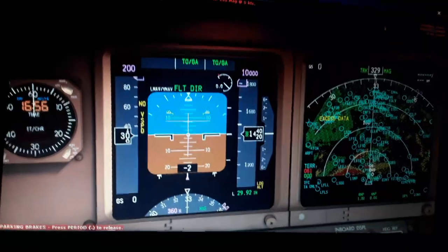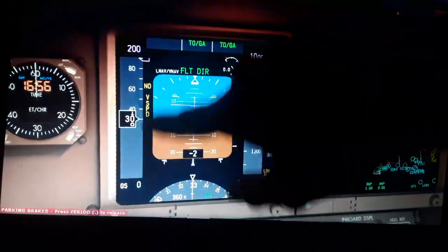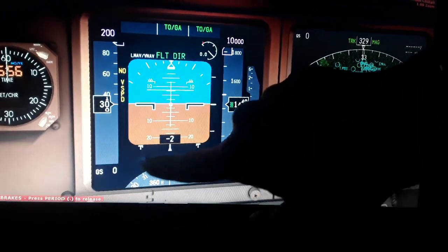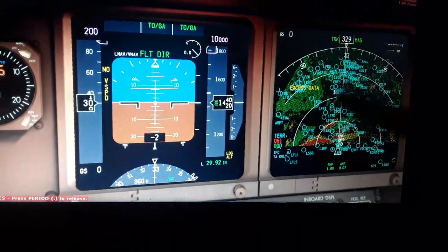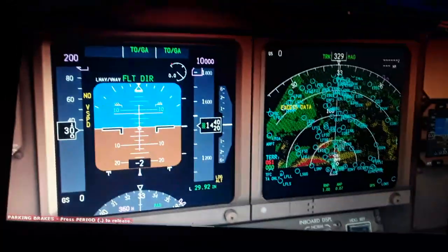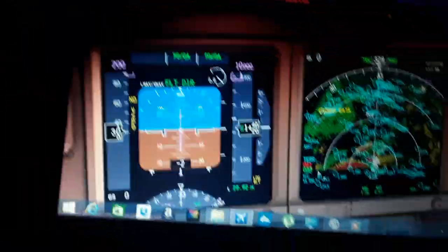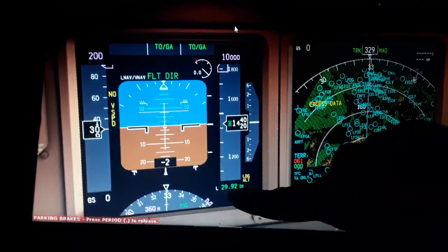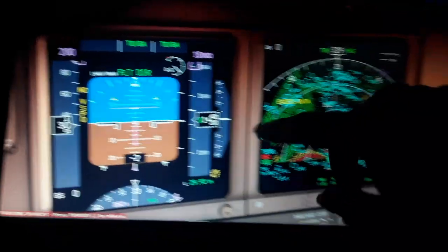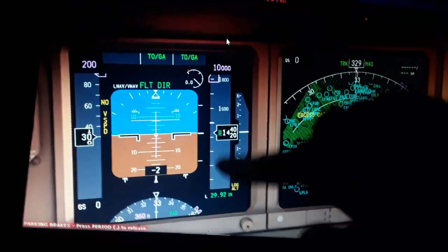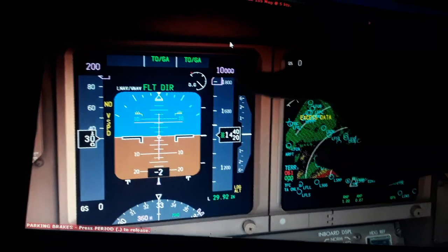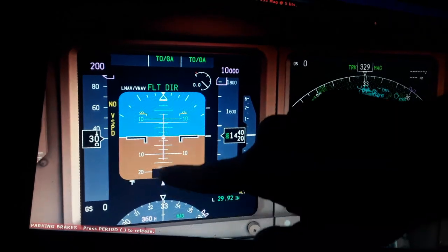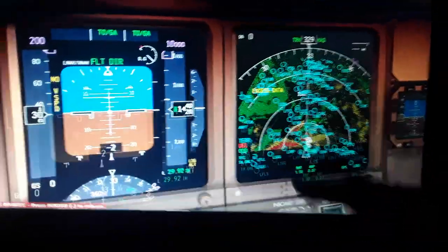You can see the airspeed indicated, the airspeed tape, the airspeed selected from the autopilot, flight direction, the panel, the ground speed, the magnetic heading and track, the magnetic north pole, the north pole, and the magnetic variation depending on where we are in the world. We have the barometric pressure of the outside atmosphere over here, 29.92 inches of mercury, the barometric altitude based on the barometric pressure and the altitude selected from the autopilot and flight direction system panel, the radio altitude above the ground level and pitch ladder in degrees.